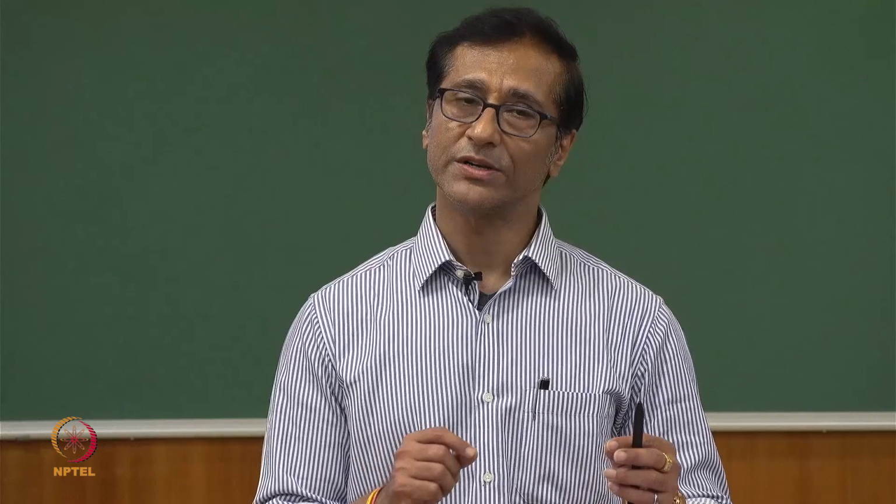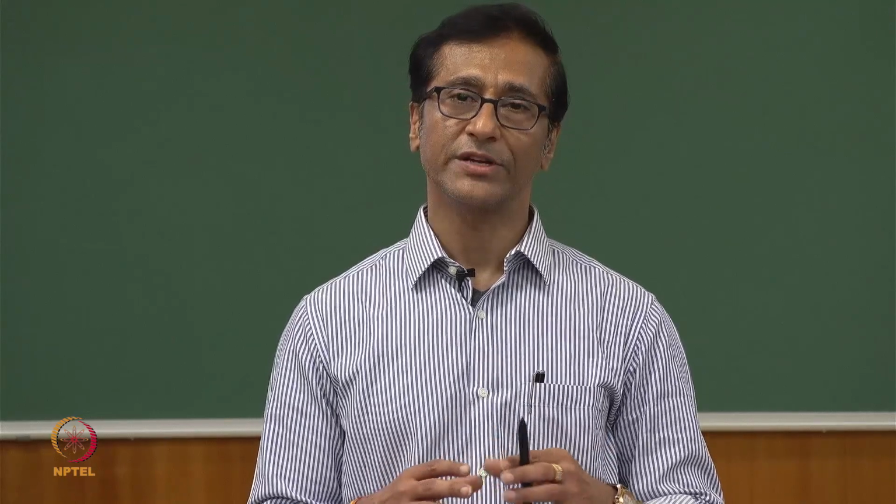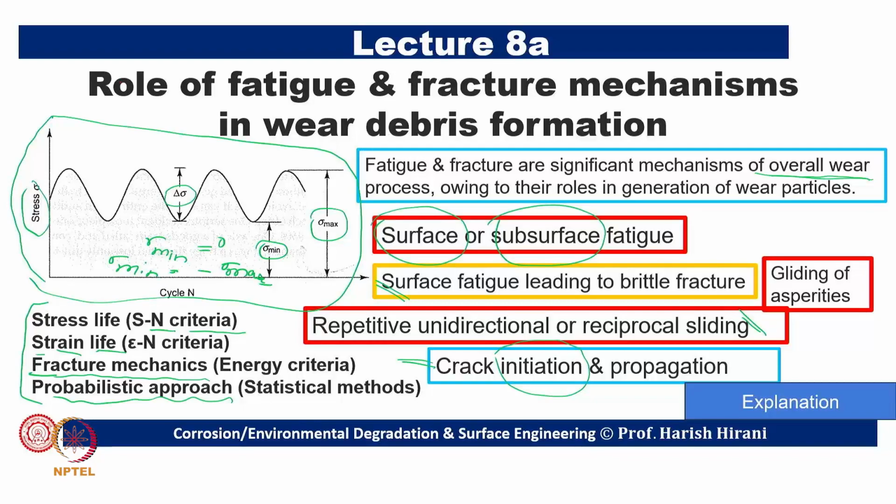Now, what we consider here is that statistical fluctuation in material property will be there. That is why we say there is a lower limit of the material strength and an upper limit of the material strength, and then we come up with a mean value and some sort of deviation. That is what we present in the material properties. That will always be important.